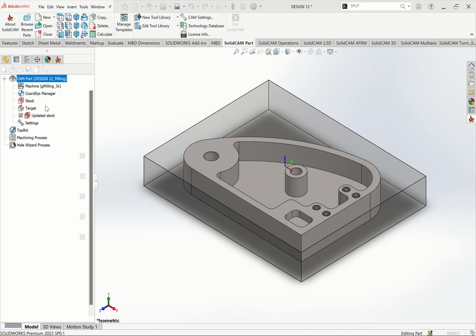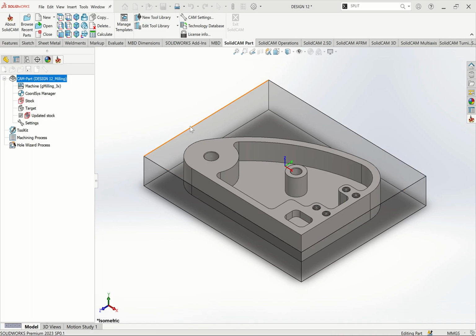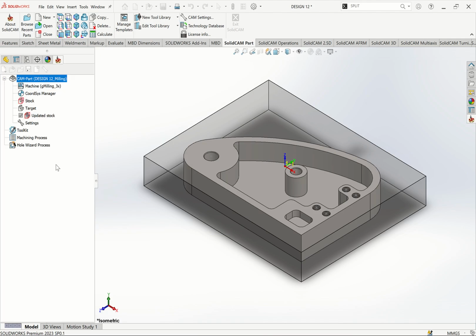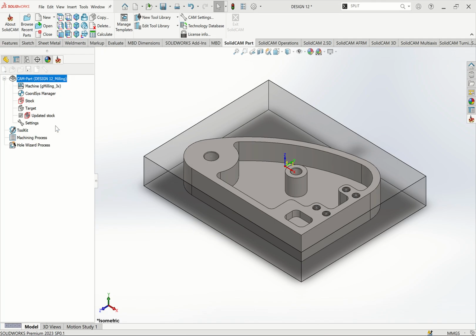And then the main objective is we are using a 3D model. That's why I made this stock, and then I didn't combine or merge. Then I changed it to transparent. So I want to show you how we can use a 3D model, and then we do pocket without cutting this inner part. Okay. So just accept, because we are using one coordinate system. Accept where it is. We have defined our coordinate system. Let's go to stock now. Define our stock.